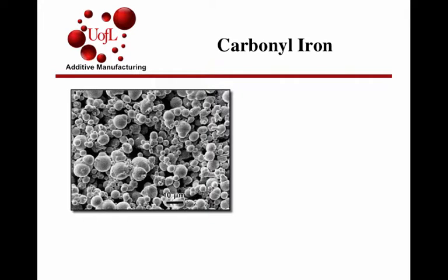Carbonyl iron. So this is through a chemical vapor deposition method where iron pentacarbonyl is decomposed as a chemical and you have a nucleation of iron atoms that begins to create these nice spherical particles. If you take a reference and compare this size bar with the gas atomized powders, the water atomized powders, you can see that there is a potential to produce much finer powders, typically 3 to 5 micron average particle or median particle size using the carbonyl route.